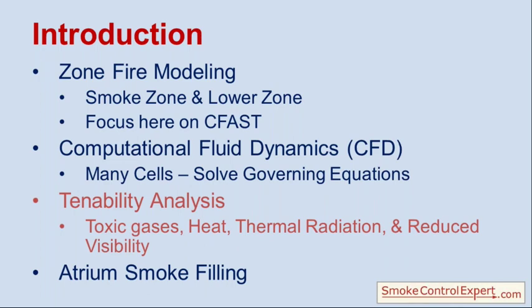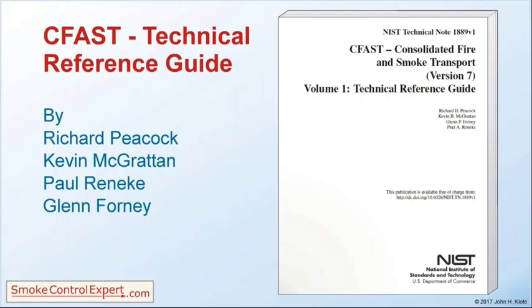Tenability analysis is used to determine if a space is tenable, and we evaluate toxic gases, heat, thermal radiation, and reduced visibility. Atrium smoke filling will be discussed later on. That's a form of smoke control for atria where we can eliminate the fans. So that's really quite a nice arrangement.